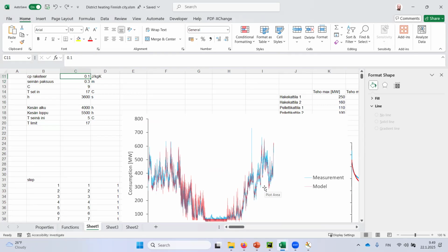So if I put Control C, you can see in here the variability increases, now the variability decreases. And that is because of the thermal inertia. If there's a sudden spike in the temperature, you can kind of write it out because you have heat stored in your building already. You don't consume so much heat if there's a sudden spike or a sudden drop. So that kind of shrinks it down.